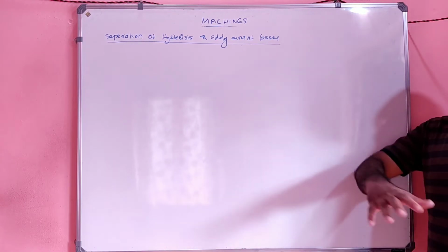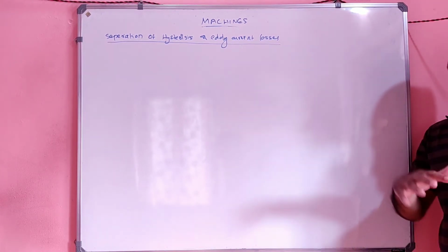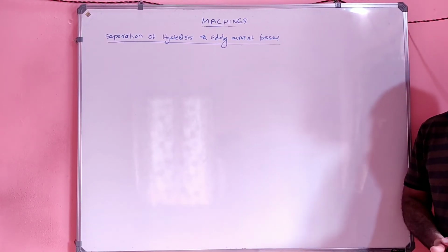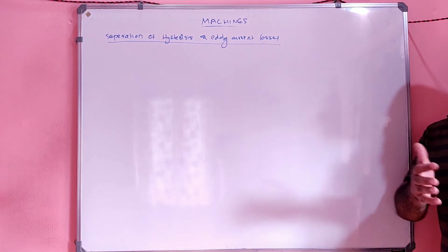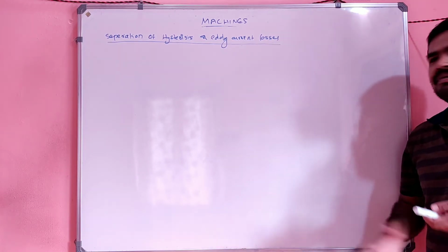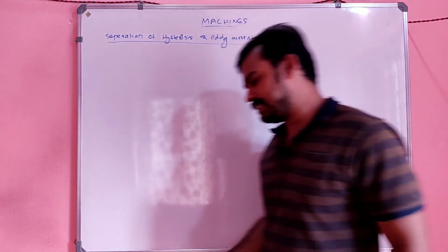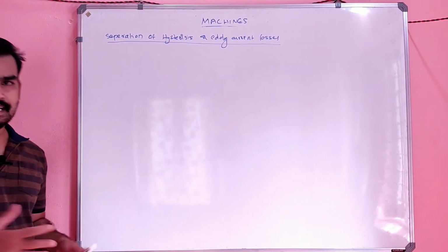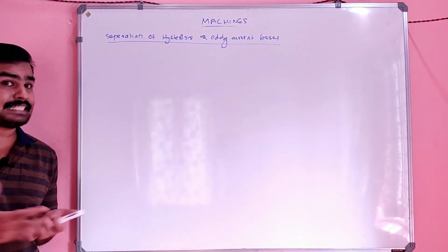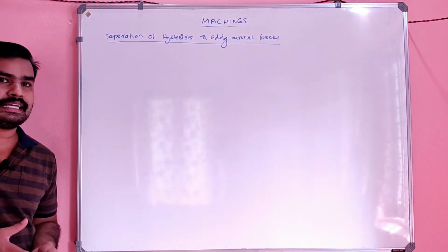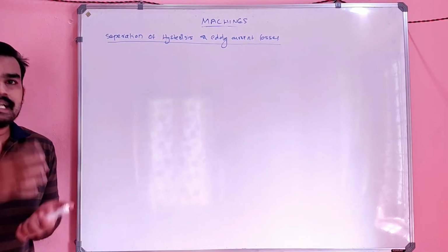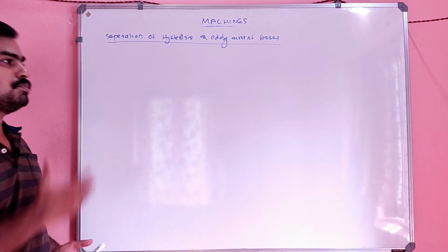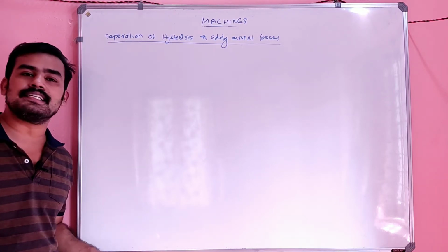And in the hysteresis loss you may see f raised to x, where the x value may vary from 1 to 2, but you can't say exactly what the value is. Combinedly you will get an iron loss, but the separation is needed. If we need to separate the hysteresis and eddy current, we have to use this technique.